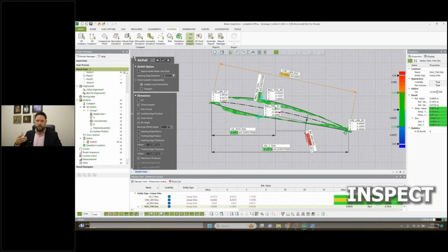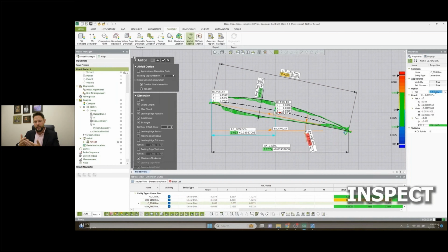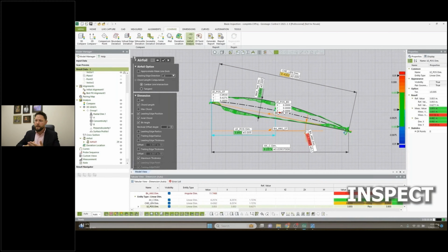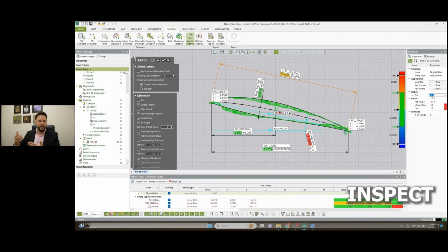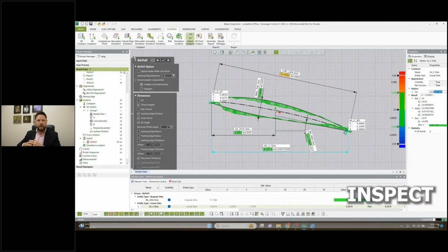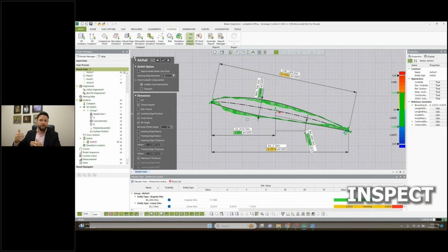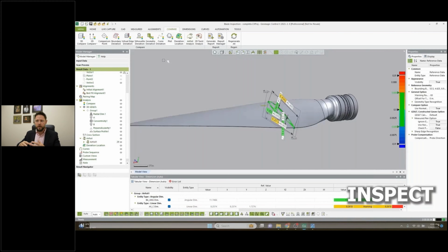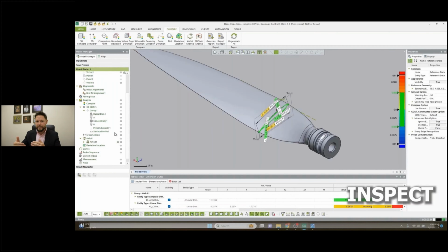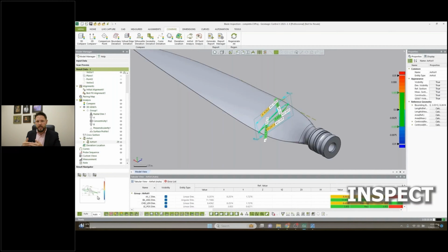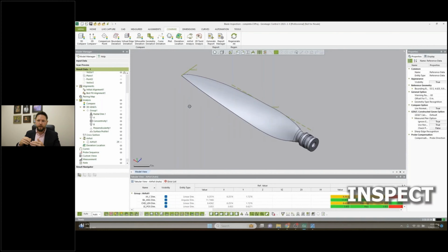All right, we can adjust tolerances here, to replicate exactly what you have on your call out sheet. And then once we're all done with that, we click the checkbox, and that applies to our inspection program. Now, you may have 10, 15 of these, or 5, or however many in your actual inspection protocol. You can set them all up ahead of time. That way it measures all this when you do scan your first blade. But that's how quickly you can apply these types of things.